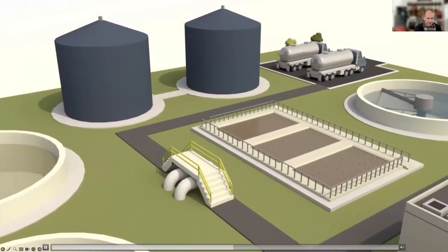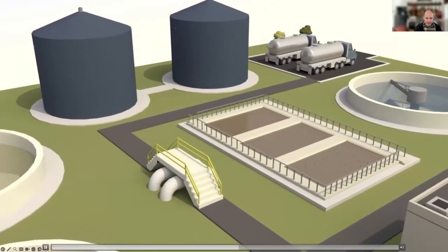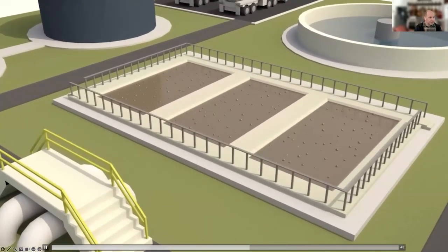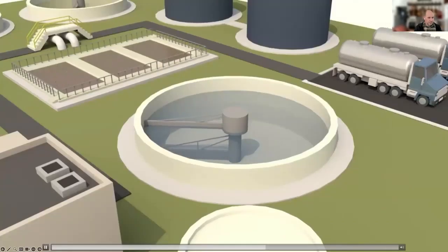Secondary treatment uses bacteria to digest the remaining pollutants. In aerobic treatment, the wastewater is forcefully mixed with bacteria and oxygen. The oxygen helps the bacteria to digest pollutants. The water is then taken to a settling tank, where the sludge again settles and is removed.